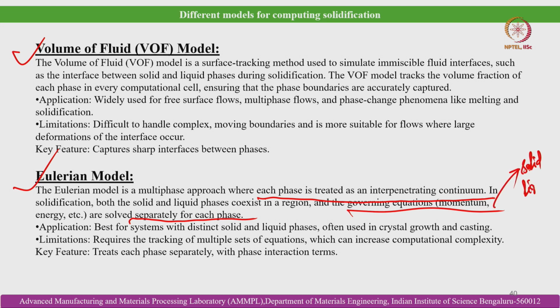In a typical solidification, I will also discuss a case study that we have solved on solidification transport phenomena for a composite in our group. You will see there that the solid can also contain multiple phases, alpha, beta, etc. Then the Eulerian model solves an individual set of equations for all these phases.